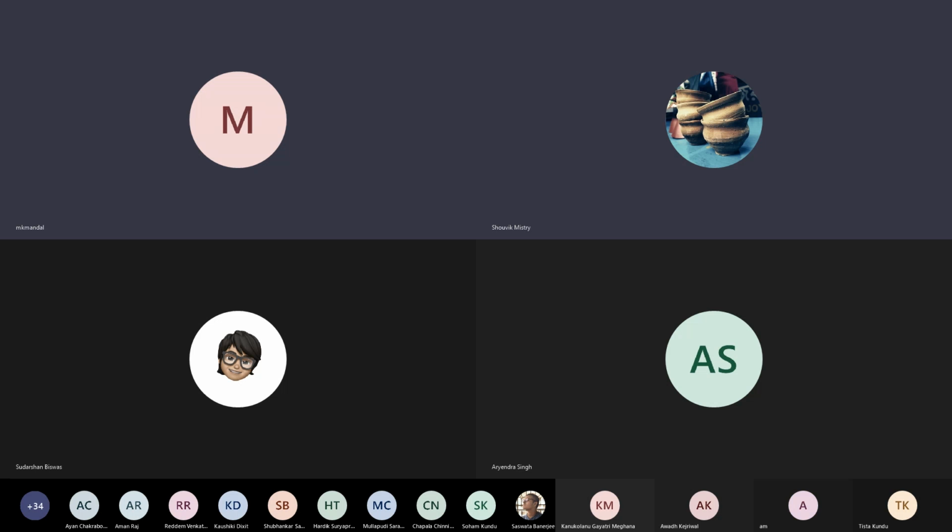Hello, sir. Yes. Sir, I actually had a simulation related problem. I was calculating the required length from an online calculator. And whenever the length was differing by a very small amount, like fourth or fifth place of decimal, the S11 minima was varying very much, from 2.4 gigahertz to 2.3 gigahertz. So is it possible?